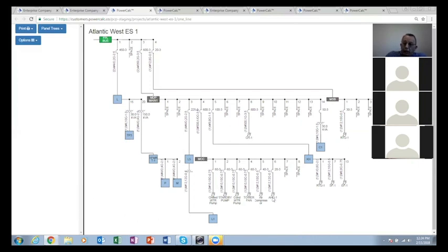Now, also in that process, if the parameters or the values of MCC need to be changed or adjusted, it will go ahead and adjust the overcurrent protection device and the conductor size for you automatically, and it will take it all the way upstream. It will adjust all that for you, unless you have set these values to be constant or taken out the automatic calculations.